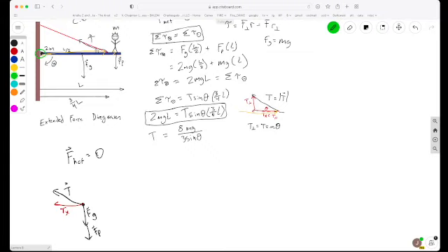So let's write out our force balancing equations. In the x direction, F net x equals 0, and that equals the sum of all the forces in the x direction. So for x, Fg and Fp don't have any x components, right? Those are both straight down. So we just need the x component of the tension. We already did that.